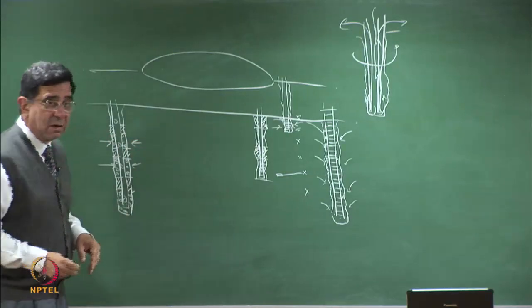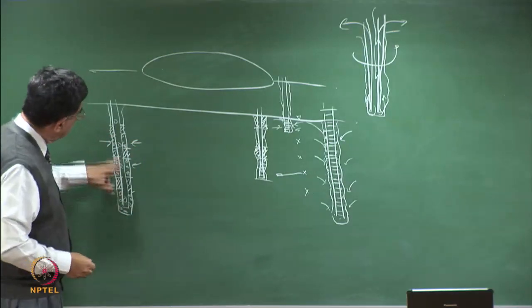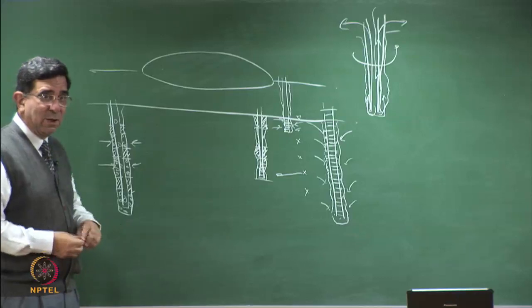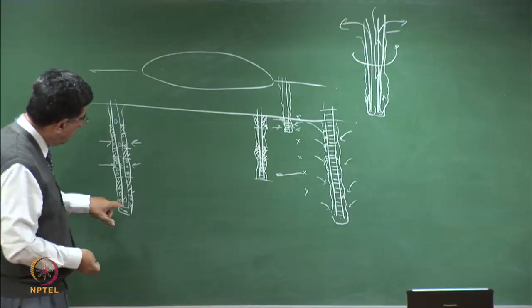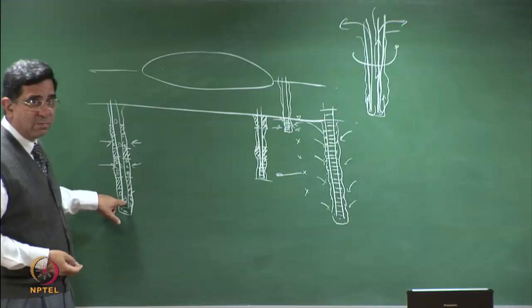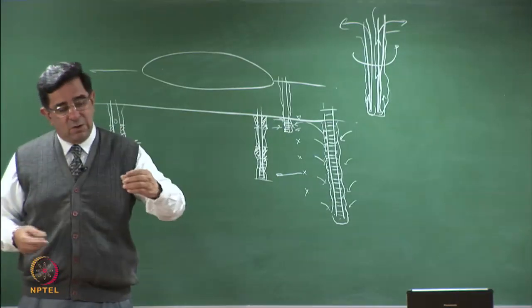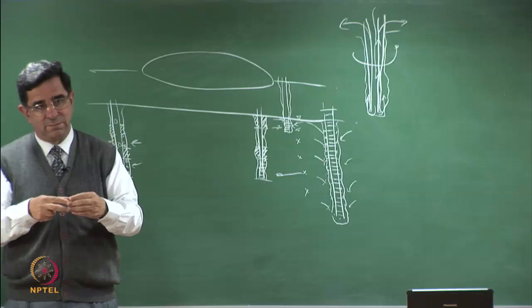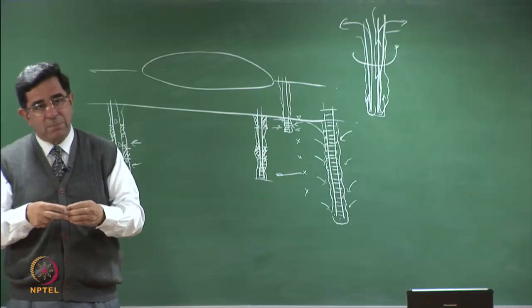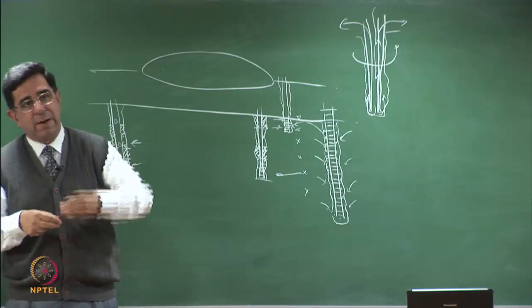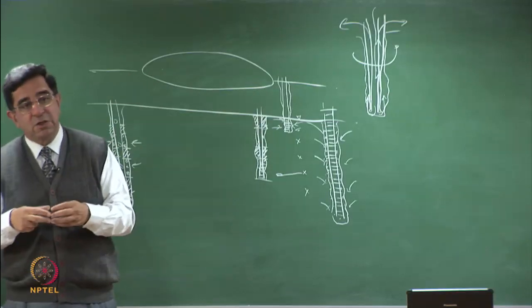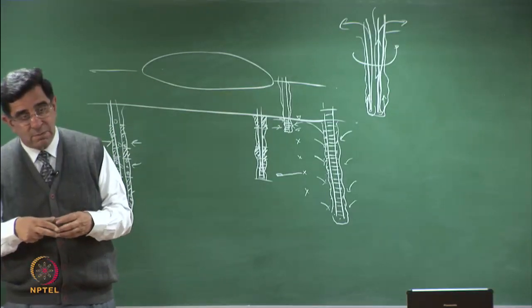So then you will say, sir, but still in this it can get mixed. So your sampler goes and docks itself on this. Shall I say it again? A sampler goes and docks itself to the hole. Then you pick up the water which comes in the sampler, take it out, throw it away. Purge it 3 to 5 times.